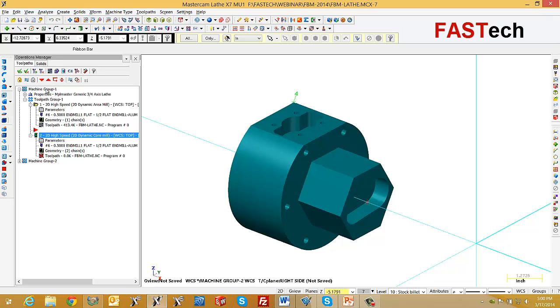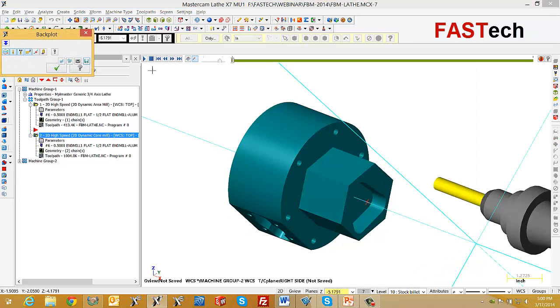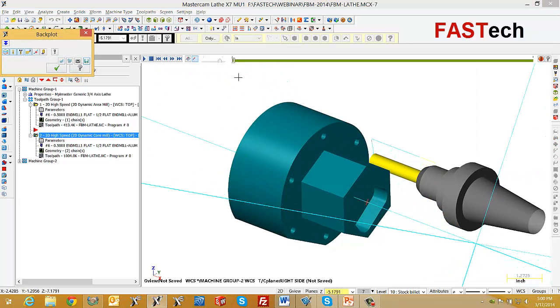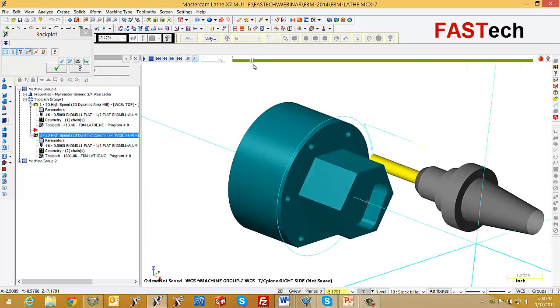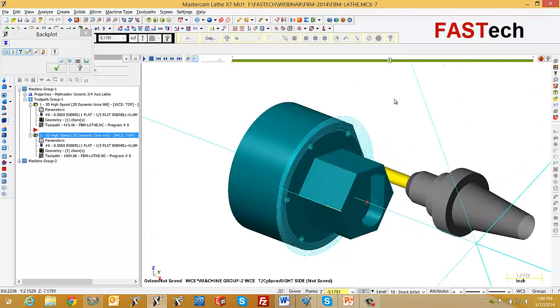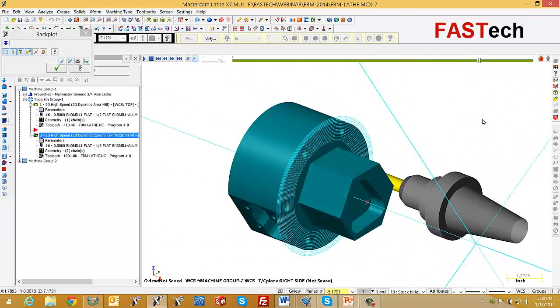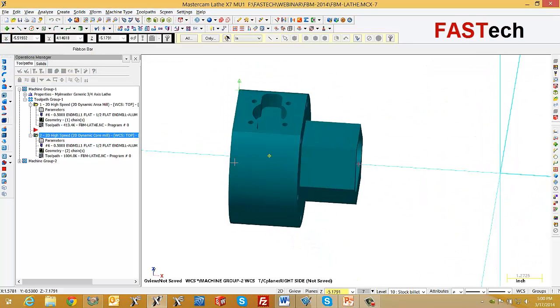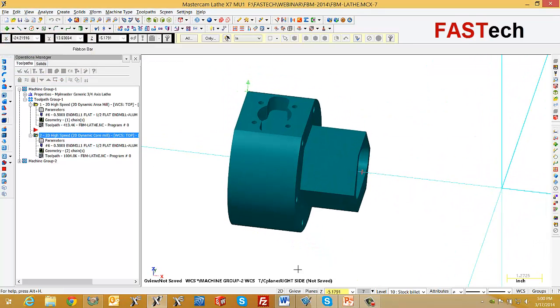Now what's the difference is now when I'm on the lathe into the second one, since I'm using the c-axis, I can simply hit S for step and you can see it make my part go around and do a c-axis cut very quickly, very easily. So even though FeatureBased is not part of the lathe, I'm able to manipulate it just by grabbing a mill, getting what I needed done, and placing it into my lathe. Hopefully this helps you.